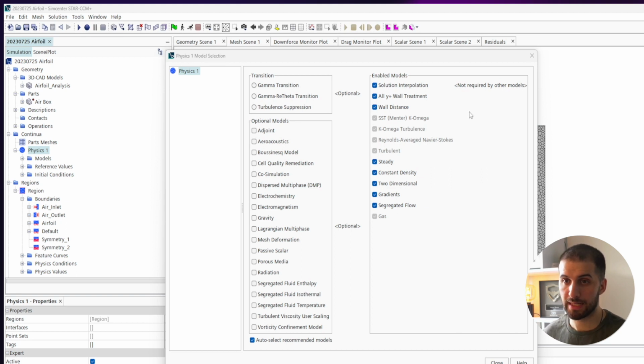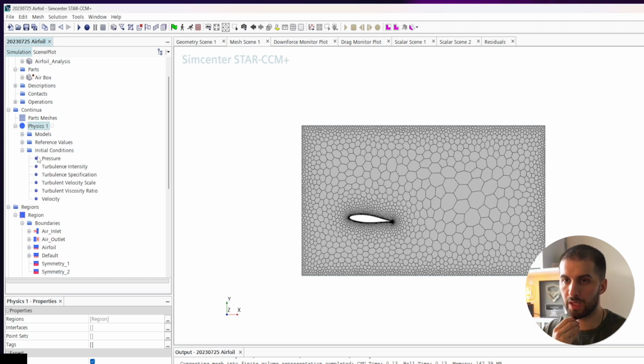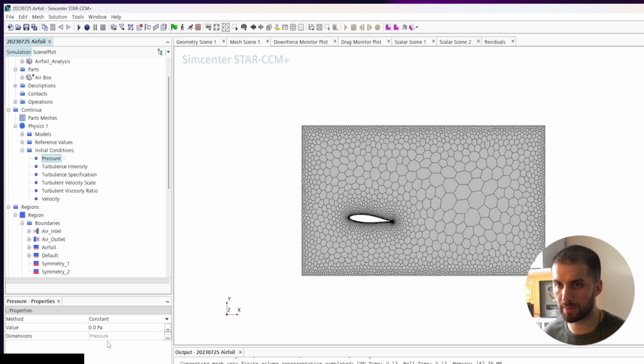So buckle up. But first, let's define some initial conditions and reports, because we have to define initial conditions, and especially for the report, it's going to be important what we try to evaluate. As you might have learned maybe in a CFD course, or maybe in one of my podcasts, it's very important to think about the quantities that you're trying to get from a simulation. So defining the report is going to be important because we want to define the quantities that we're going to have a look at in post-processing to evaluate our flow around the airfoil: lift, drag, and a few others that might be important. But again, it depends on the use case what quantities are going to be important.